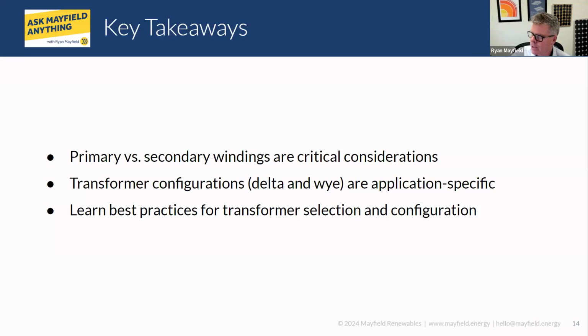I guess this was a question that came up that I'm not sure how quickly or easily we can answer, but I'll give it a shot. On transformer configuration and phase loss testing, does the transformer configuration have any impact on that? When we're doing phase loss testing, is that something you've seen? I have seen, when people are doing a phase loss test, the transformer, while being energized by two legs, will still prop up that third leg. With it being a 3-limb core design, it does try to prop that up.